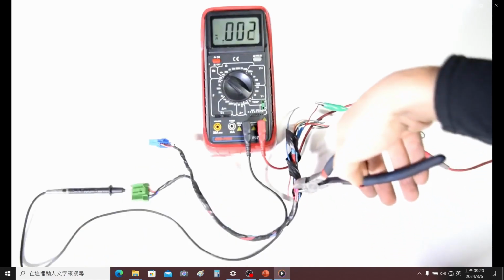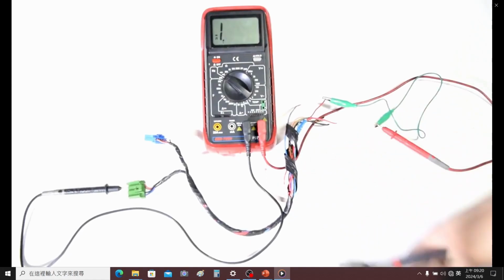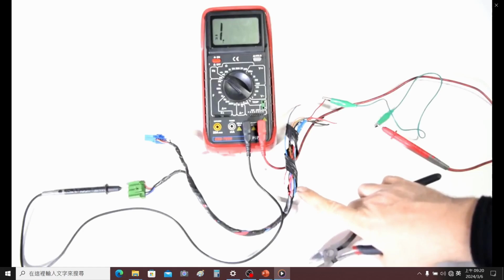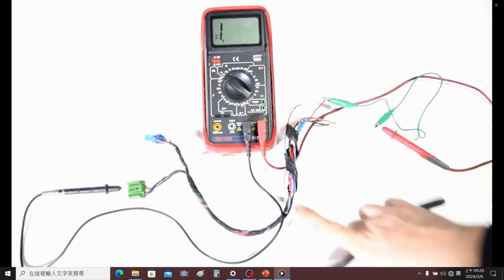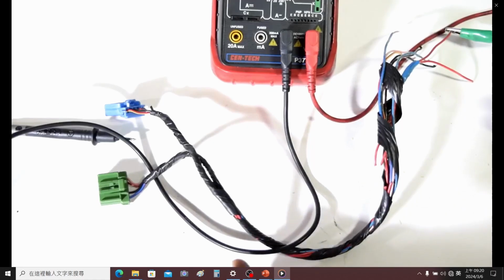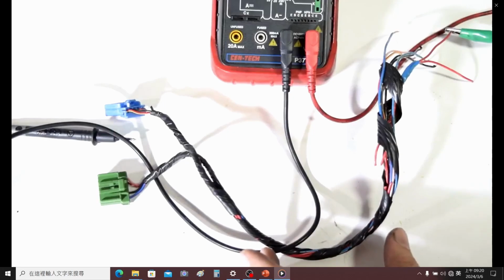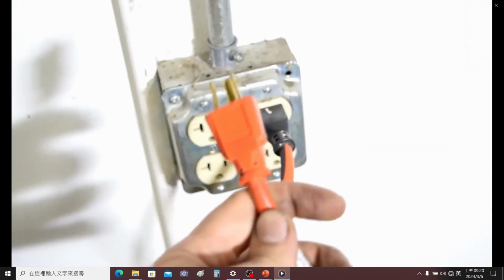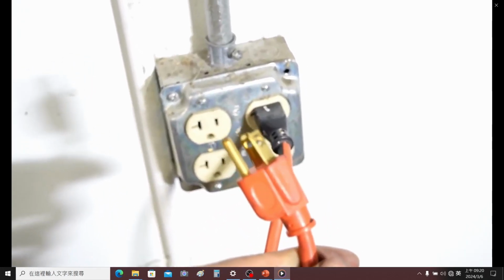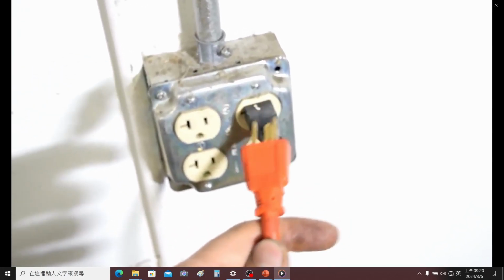If you do this and you don't hear a beep, it means there's a break somewhere in this wire, in our case maybe a cut or a burnt wire. I did this test on a rather small scale, but it can be done on a much larger scale, on larger circuits, or even smaller ones, like the motherboard of your computer. A word of caution though: whenever you test for resistance or continuity, make sure the device is not powered, so either unplug it or remove the batteries.